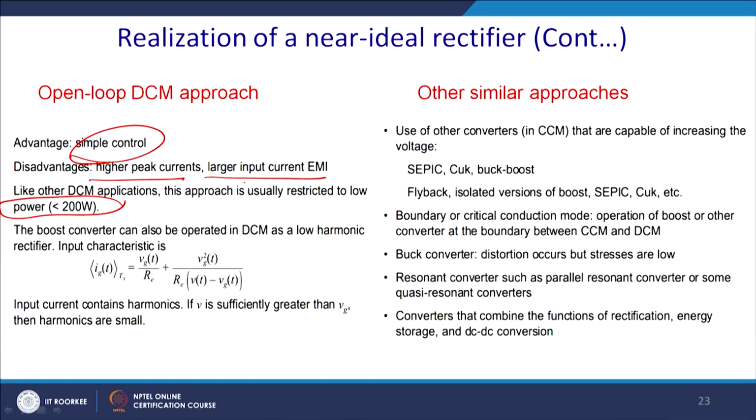The boost converter, though the buck operation is there anyway, finds its application mostly in UPS. Most of the UPS will say that it is a power factor corrected UPS. So, in that power factor corrected UPS we incorporate this boost topology. After this boost topology we follow it with a half bridge inverter that will feed the power to the inverter. So, a different kind of inverter comes into the picture.